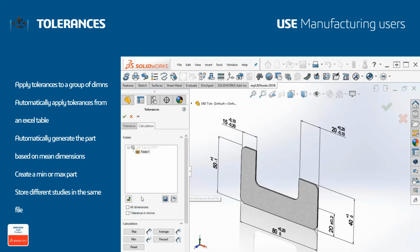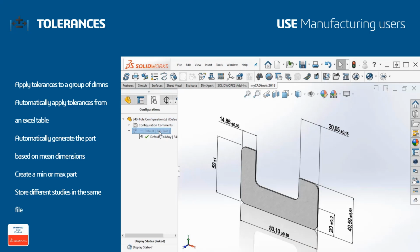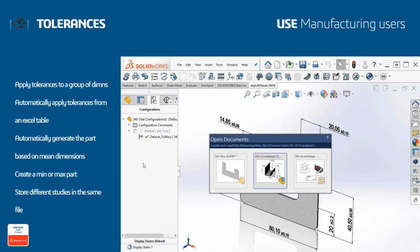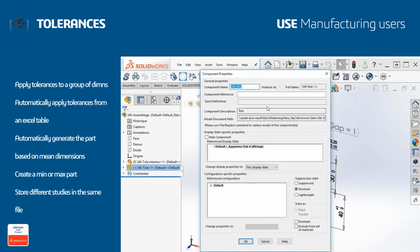The second tab allows me to recalculate the dimensions according to my tolerances. In this case, we want to look at average values. A configuration is generated within the dimension at those values, and I can quickly switch to this in my assembly to understand the impact this has on any clearances. If you are manufacturing to tolerances, this is a great addition to help check and define appropriate tolerances on your model.